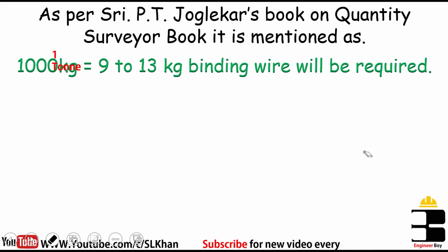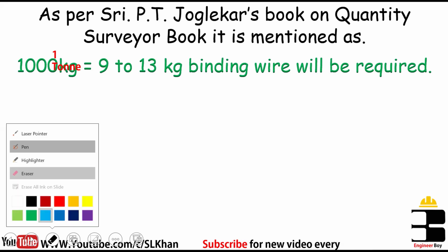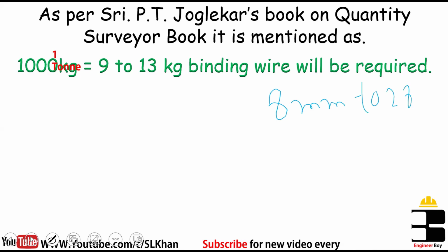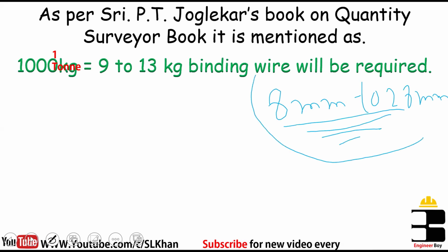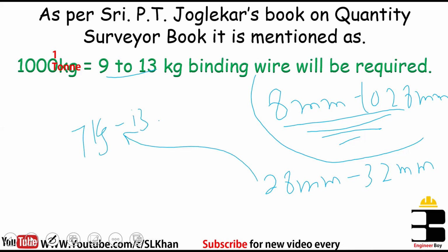However, this can be different if the bar's diameter is a little different, from 8 mm to 28 mm. So if your project contains bars from 8 mm to 28 mm, and your project is 1000 kgs, then you may require 9 to 13 kgs of binding wire. And if your project is just from 28 mm to 32 mm, then you may need 7 to 13 kg of binding wire.